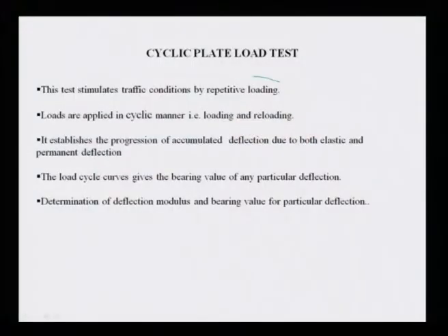Last time we discussed the cyclic plate load test. Once again, this test simulates traffic conditions by repeated loading, and loads are applied in a cyclic manner, I mean loading and reloading. It basically establishes the progression of accumulated deflection due to both elastic as well as permanent deflection.